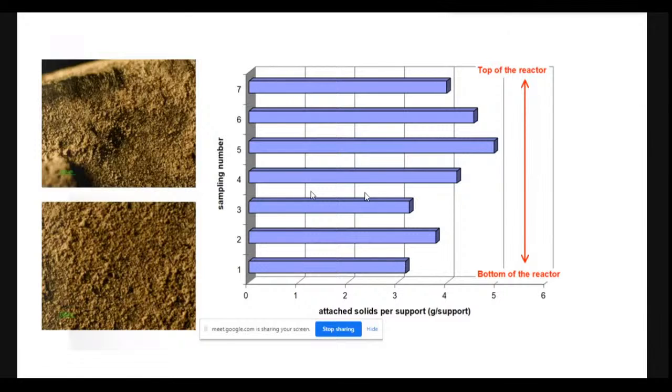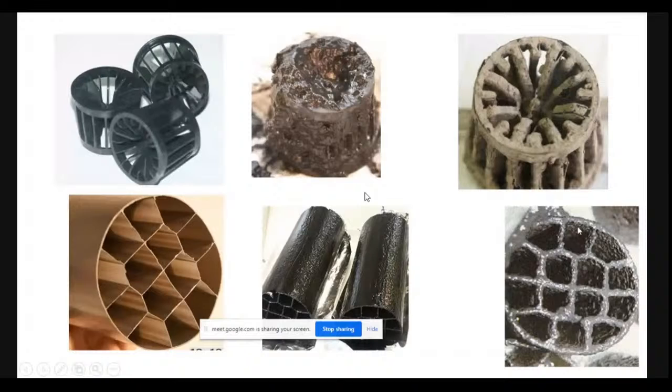Now the problem that we encountered in these two is that, though in the honeycomb one the thickness is more, it has a very thin biofilm, because what happens first is that you get a mineral coating on the PVC surface before the microorganisms could get attached. So that indicates that they cannot get directly attached to PVC material, and thereby you lose quite a large amount of area to the mineral coating. Whereas in the case of the polyethylene material, that mineral coating is not there, and thereby you get 100% biofilm, which is more active than what you have seen in the PVC one. All right.